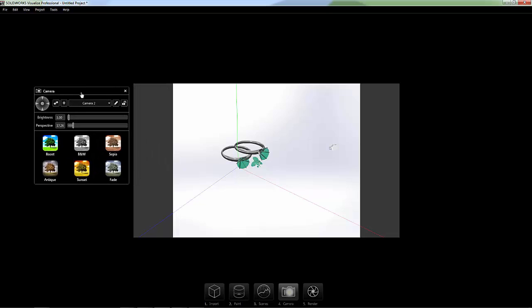So the main reason for doing this, though, as I mentioned earlier, is we don't want to be a slave to our computer, and every time we finish a render or set up something new, have to go back in and hit that render button, let it do its thing. All right, we didn't like that one. Let's switch it a little bit. I'll set up multiple cameras in a couple different places where I think I might use them, and I'm able to render those all simultaneously.